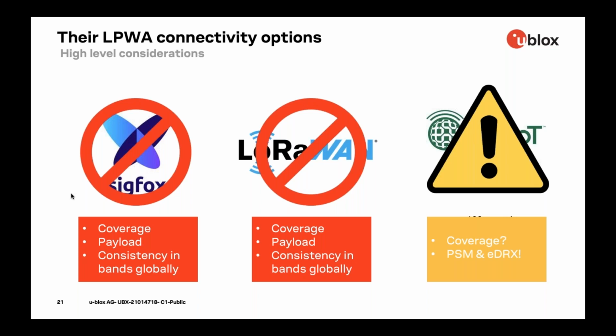You could put that out in a field on a different network, and suddenly your battery life's been reduced to 1 year purely because of the way that these timers are working. So it's very difficult for you as the designer of the product to reliably factor those things in unless you know exactly where that device is going to be used and the network that it's going to run on.